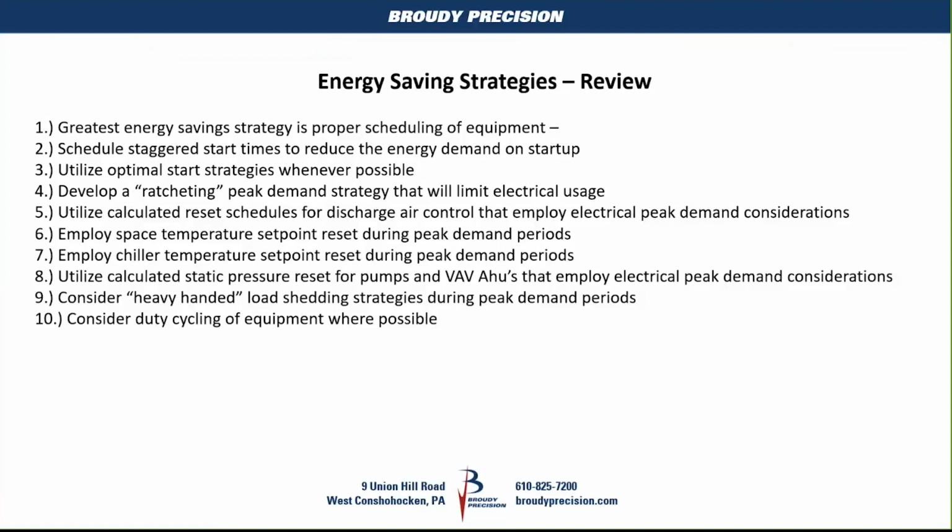Now, that may not make a whole hill of beans with one air handler, but when you start moving that to 15 air handlers or 15 pumps that are controlling pressure through the static pressure reset, it starts to add up. And again, this is happening through the demand interval. And what will happen is it goes right back to normal when we're back into our new demand interval.